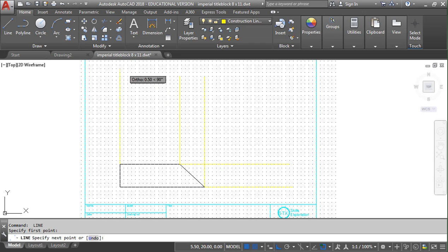Now you can see I tried to create a line and it went to the end because there's an object snap on, so I can hit escape. I'm going to create a line, just starting way out here. And then my last line I'm going to create is somewhere up in here. The last line I'm creating is going to be at the intersection right here, at a distance of, I don't know, 5 at an angle of 45 degrees. That's just going to put a line up on an angle.